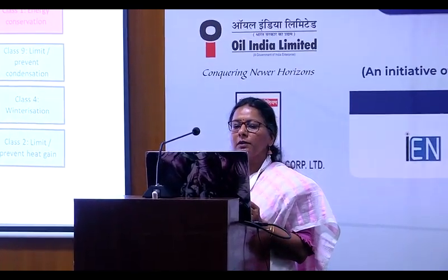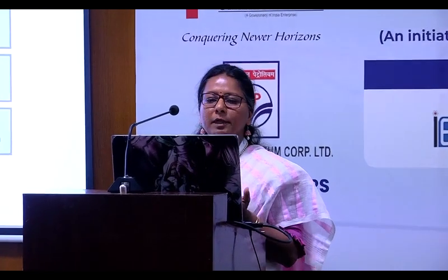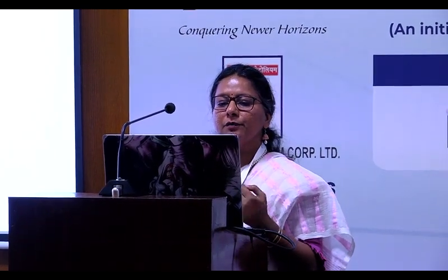Based on our final requirement, the reason for selection of the insulating coating is whether it is fireproofing or thermal. Fireproofing is also one of the aspects where we have to ensure that corrosion doesn't occur on the structures underneath the fireproof coating. Then whether it is for thermal insulation or acoustic, that I already spoke of. For hot insulation, mostly for personnel protection, we can go ahead with thermal insulating coating.